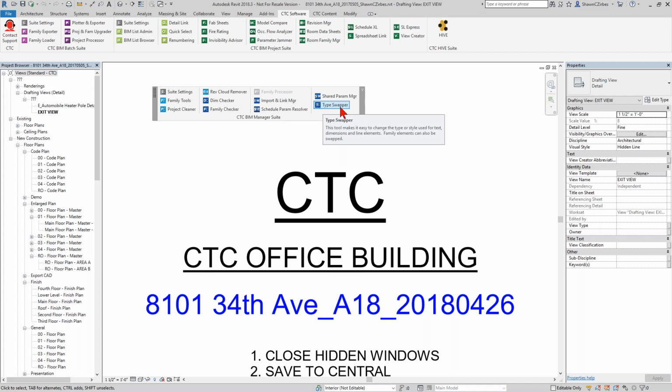So the major things that I, as a BIM manager, spend a lot of time tracking down, fixing views in my project, kind of cleaning things up in general, finding overridden dimensions, fixing imported content, and actually swapping certain styles out across my model for those that I really want people using instead of old standards or imported CAD exploded stuff. This can really help me with that workflow.